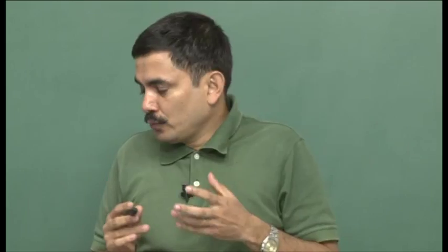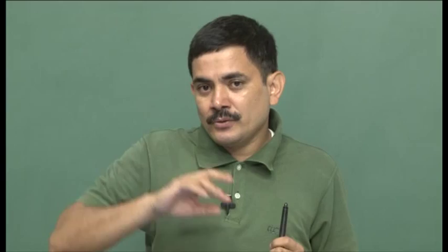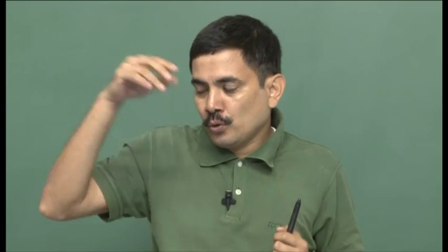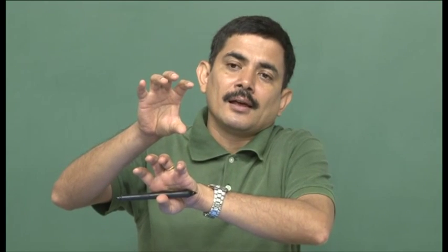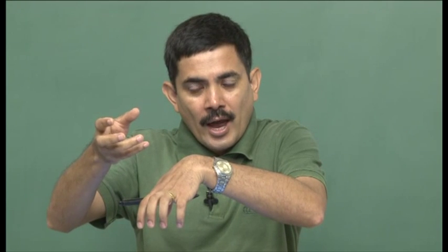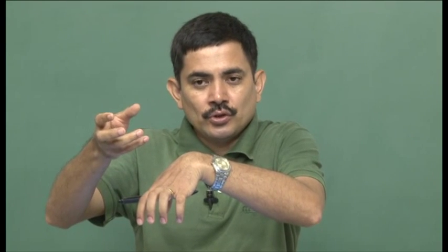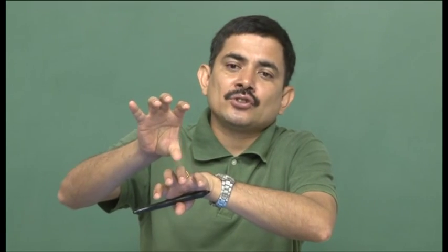How should I pair? There are interaction metrics that are used quite commonly to figure out which pairing gives us favorable interaction. If you remember multivariable systems, the off diagonal terms G21 and G12, when you are trying to control both Y1 and Y2, introduce an additional feedback path. The off diagonal terms can give too much interaction, and for a pairing that has been chosen appropriately, that interaction can be minimized or mitigated.